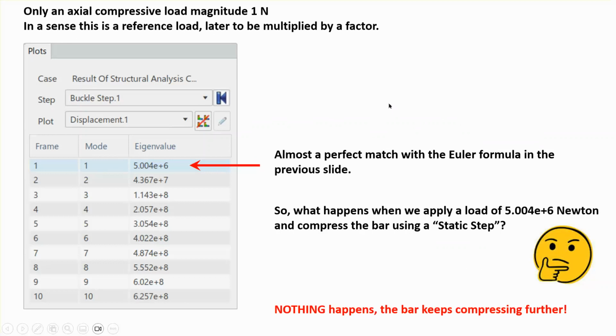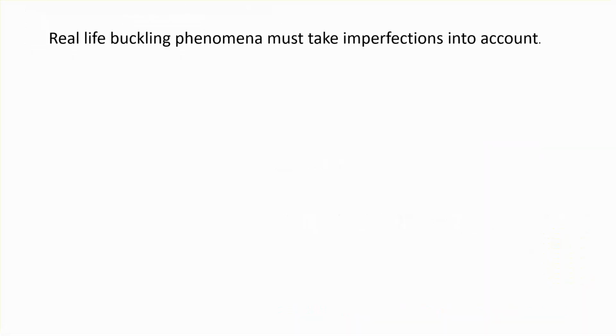You'll see that. And this leads to tutorials 5 and 6, which say, okay, the problem is that the assumptions that I made, either in the Euler buckling analysis, the Euler formula, or in the finite element, assume that this actual load is applied perfectly at the centroid of that cross section, and there is no offset.